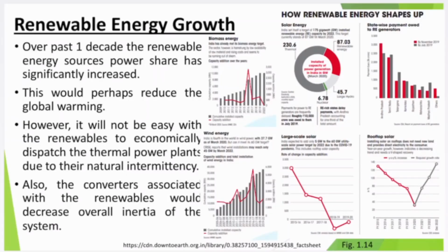This is because those huge generators do carry inertia within them. That means they do store some energy within themselves. As and when there is an oscillation of requirement, they provide that inertial power. Okay? And hence we don't realize any mismatch between my requirement and its availability. But in the case of renewable energy, wind to some extent is fine, but especially solar, there is no rotational part. If you do not have a rotational part, then you do not have inertia, energy or power. And because of which there is a lot of challenge.